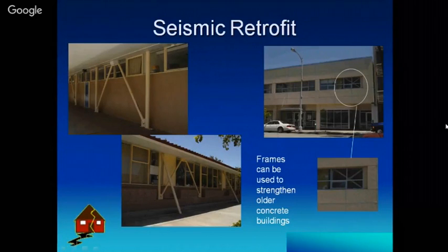It is the same as your bike suspensions or bike shockers. They try to mitigate and dissipate whatever force is being generated by the potholes of the road. So the thing is the same. We have the fluid viscous dampers which try to dissipate and mitigate the energy of the earthquake, making the structure safe.